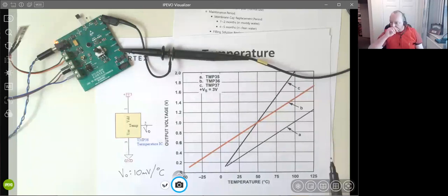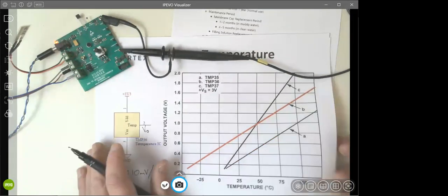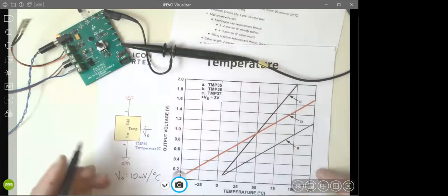Ruth, I'm sure you remember with decoupling, your decoupling circuit, we had your capacitors all blocked together, and John Grant says, no, spread them out a little bit more. So, yes, the layout. And in particular, put the small value ones closest.